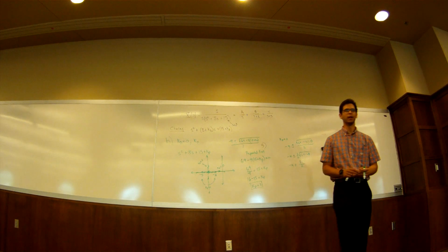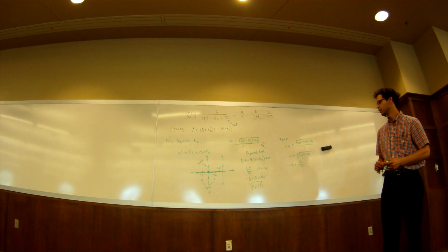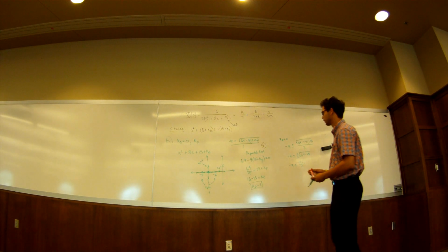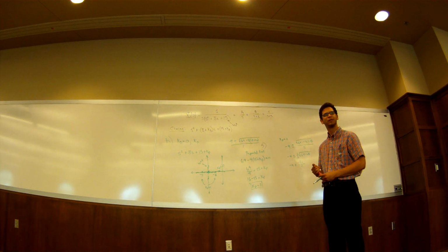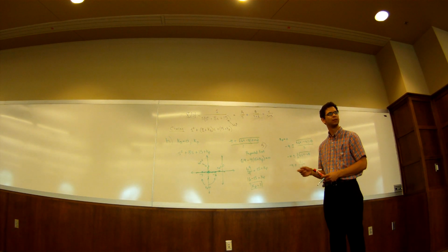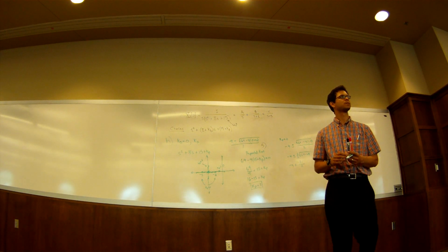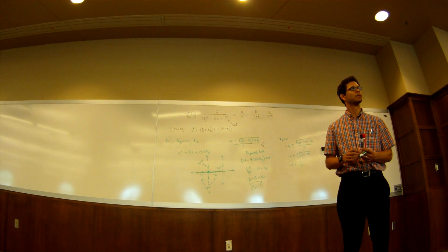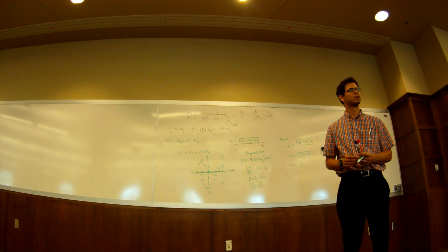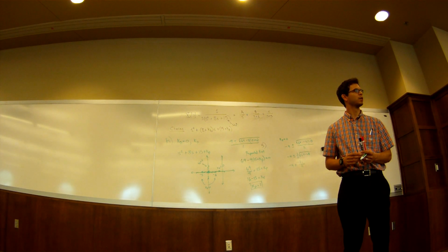But why would you ever do that? Now, did I ask you to specifically find where it went unstable? What did I say? What did I specifically say? Yeah, so just say Kp negative. If you make Kp negative, it'll go unstable.